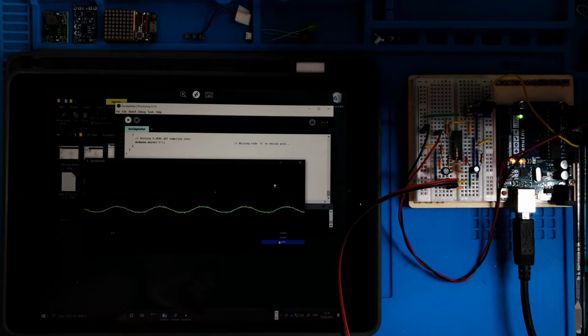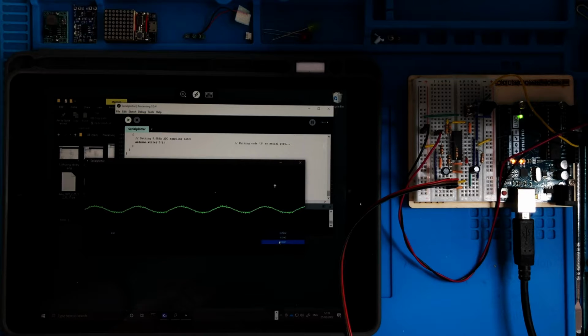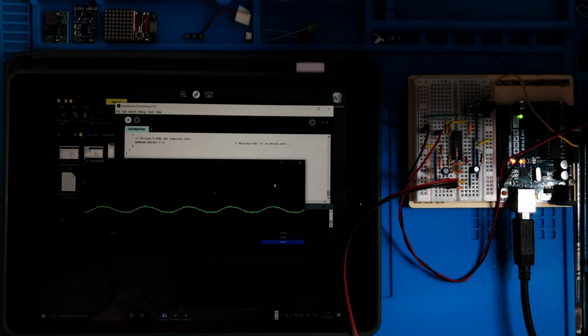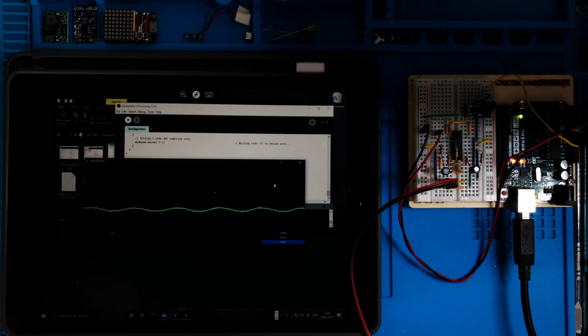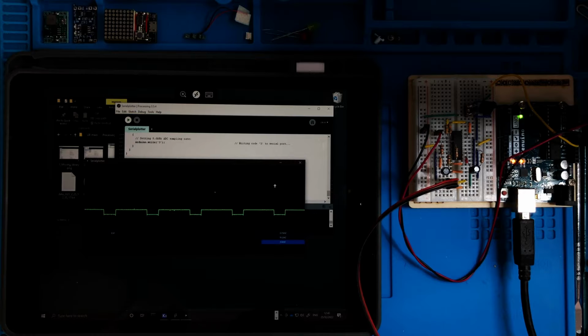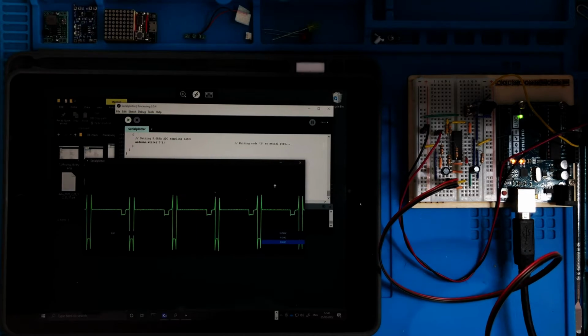Another thing that I can do is, oh, sorry. Now I know the thing. I'm not connecting my Arduino to my laptop computer, but to my big computer, which is not a laptop, and so it's not connected through a system that is running on batteries. So I have to do one thing. This is why we still have this oscillation, because it's picking up from the mains.